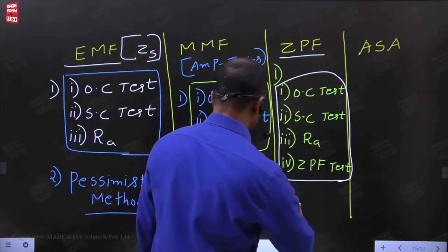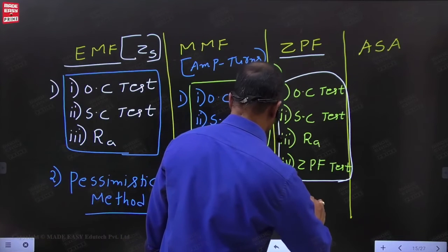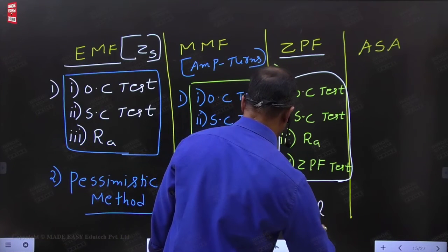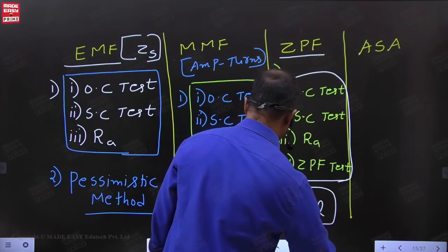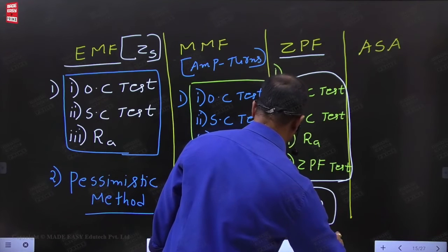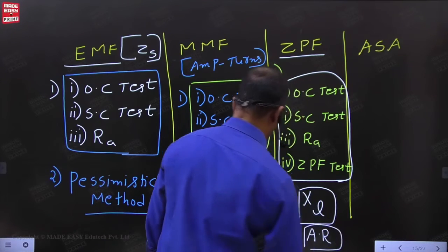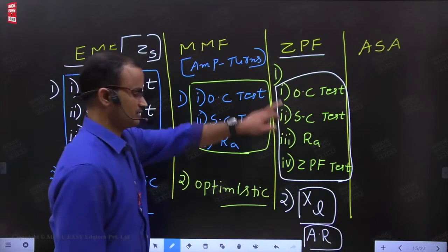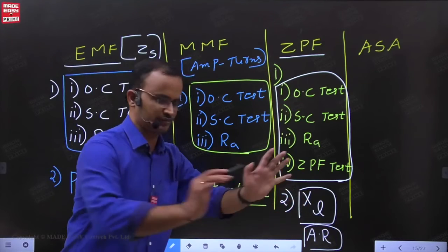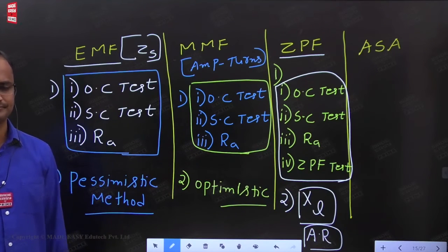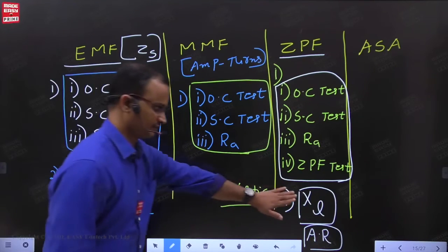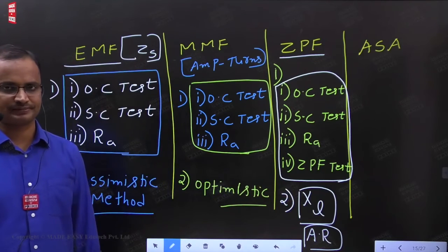The second point is that in the ZPF test, the leakage reactance effect and the armature reaction effect are separated.